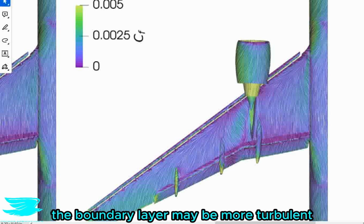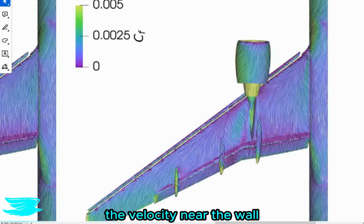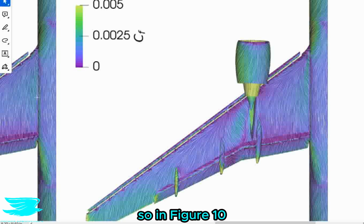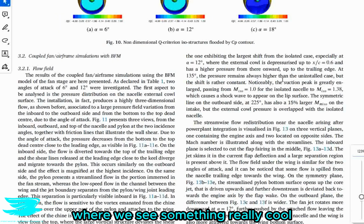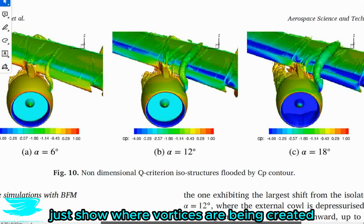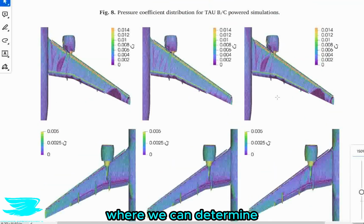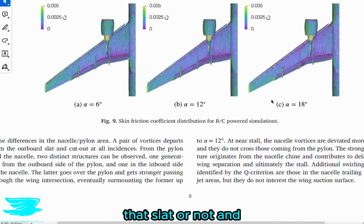The boundary layer may be more turbulent, or maybe something else, I don't know, but it's probably more turbulent at the very least. The velocity near the wall is much higher than the surrounding regions. So in figure 10, we have a really cool figure. We have these criterion isosurfaces shown here, and they effectively just show where vortices are being created. And this is what I was talking about earlier, where we can determine whether this vortex is really coming from that slat or not.